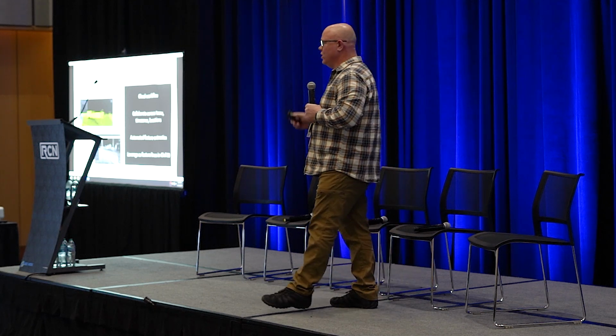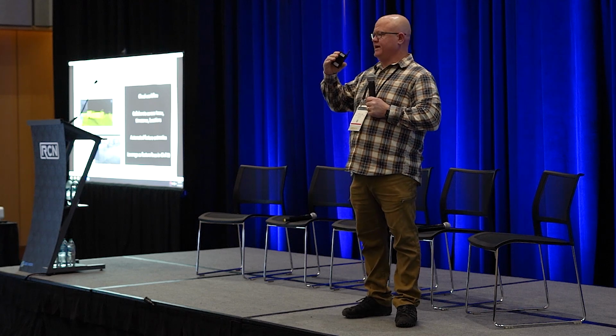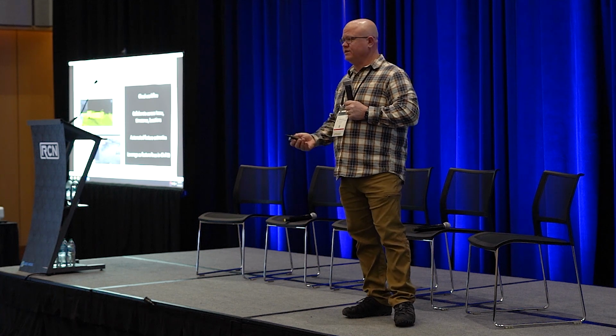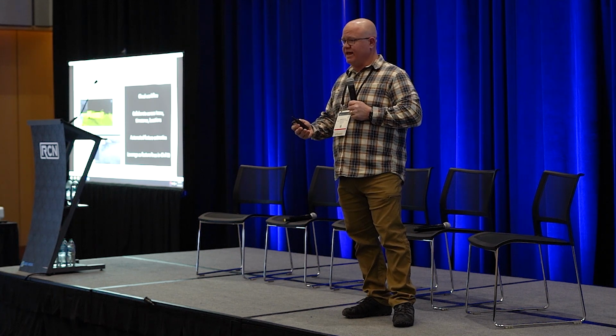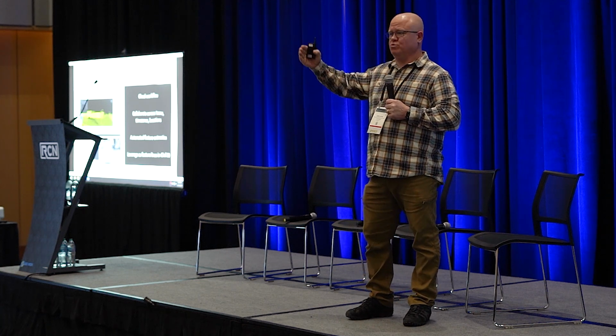Now, why would I want those linear features? All right. I would want them so, number one, I could bring in those linear features, they come in as feature lines in Civil 3D, and I can generate a lightweight surface from those feature lines, okay? Rather than bringing in a 20 billion point cloud and trying to build a surface from it, which you can do, you can just bring in the linear features and generate the surface from that, and I'm telling you, it's just as tight, okay? Because you can actually tell it how close you want it to sample.